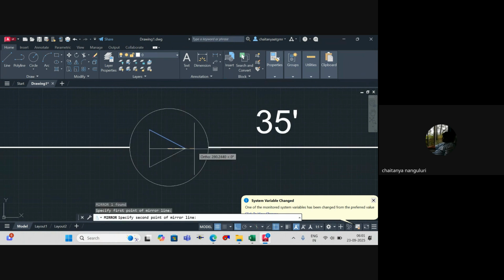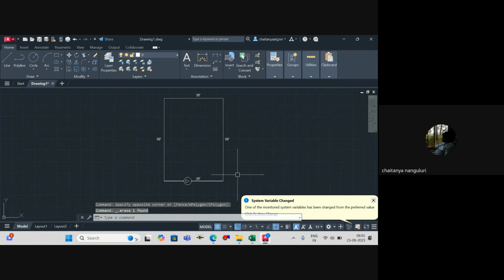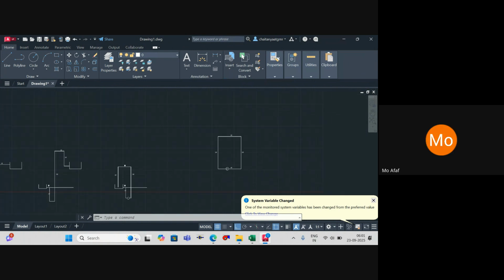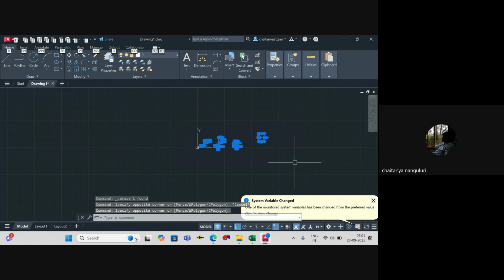Water is just recirculating in the piping, let's say. For fun, I wanted to recirculate the piping. Now, what is the static head over here? Zero, obviously. So for closed loop systems, for example, from AHU to chillers, no matter what the height of your AHUs is, the static head will be absolutely zero. Understood or not? Clear? Yes.